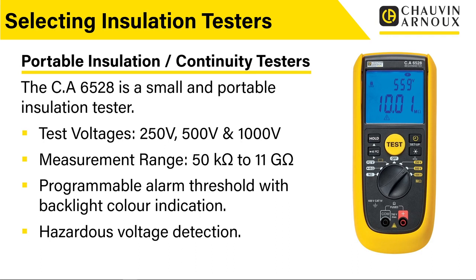And that means we've got a good range of values on this. It's got a programmable alarm threshold with backlight colour indication, so you can actually set at what resistance value you want the backlight to change to red and tell you that it's failed or that it's lower than you would expect. So it gives you a nice clear indication. So if you're testing quite a lot of things in one go, you don't want to be just staring at the screen all the while seeing that going up and down. You can actually hear and you can see that alarm function. It actually tells you that the insulation has got a problem.